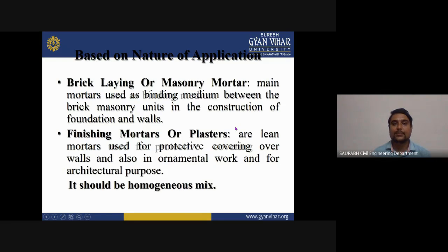Now we will see classification based on the nature of application, where mortar is categorized according to the nature of the application. Here is bricklaying or masonry mortar. It is the main mortar used as a binding medium between brick masonry units in the construction of foundations and walls. Then there is finishing mortar or plaster,